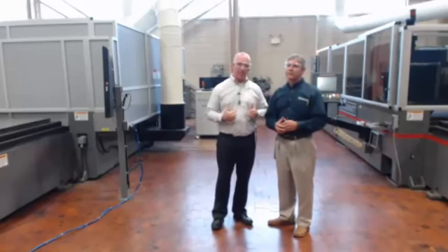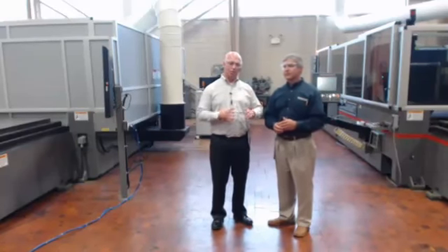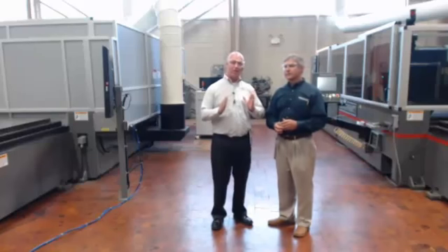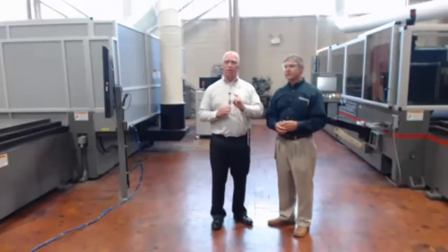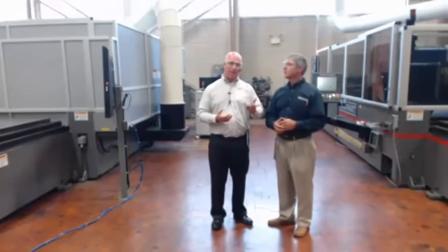What we like to receive is a true actual representation from the model into SigmaNEST. So we want an 8-inch part with a 1/4-inch hole to actually be represented by an 8-inch part and a 1/4-inch hole. And from there, we're going to go ahead and nest those parts. We're going to call that part a candidate for common line nesting.